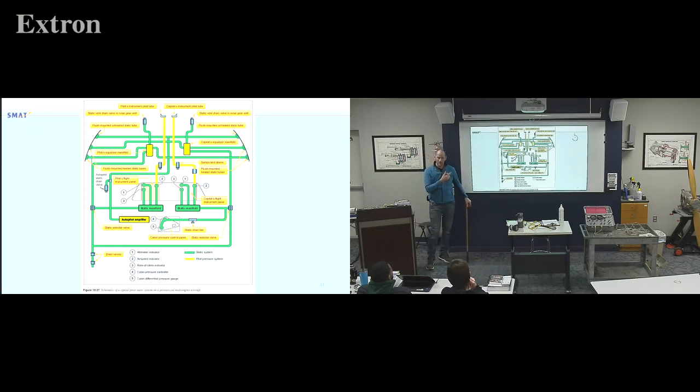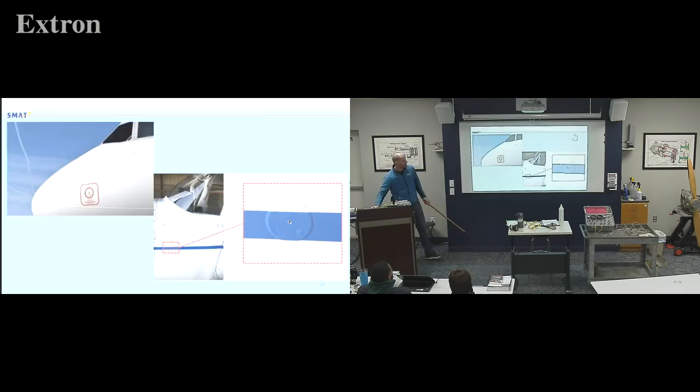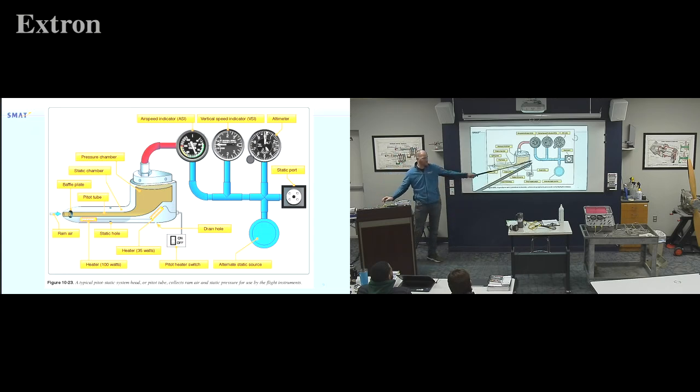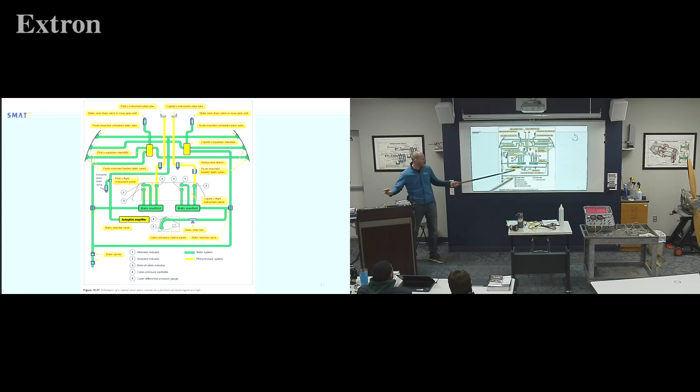I mean, if you got on the Beech and we go to do this test, and it doesn't pass the test, and they say, okay, go find the leak. Especially because our static system is typically, we're going to call it a negative pressure. We're not going to want to take shop air and add it to the system and then look for where the bubbles are with soap bubbles, because normally it's a negative pressure compared to atmosphere at sea level, right? So trying to find a leak is tough.